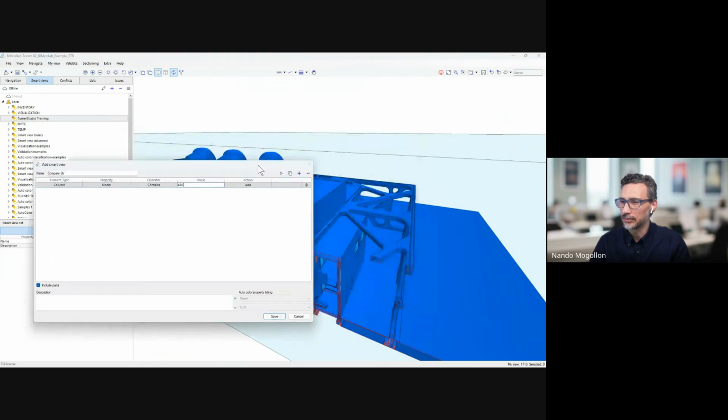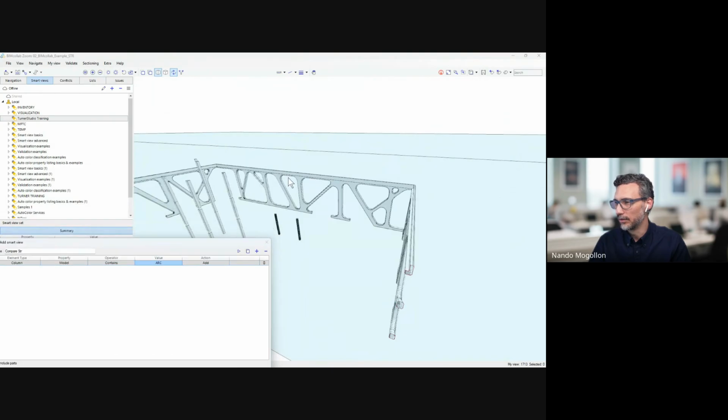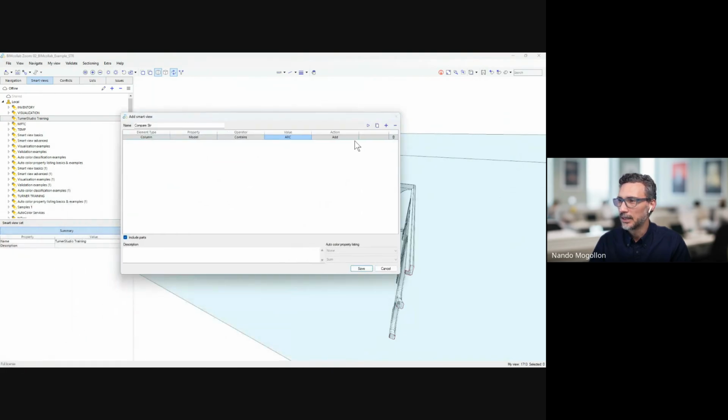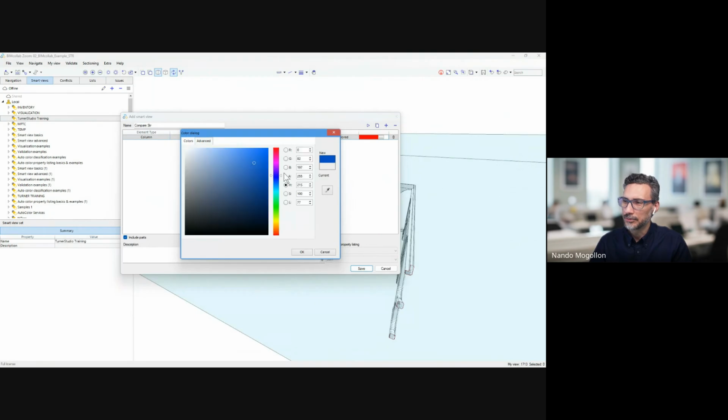that contains the acronym ARC. That's going to be the architectural. You want to check, just click on equal. Okay, all of those are meant to be columns. All right. I'm going to add them, but I'm going to add them and set them to a specific color. So I'm going to say add and set color. I'm going to say blue, but actually I'm going to give it a little bit of transparency with this alpha channel. So I'm going to say 100.